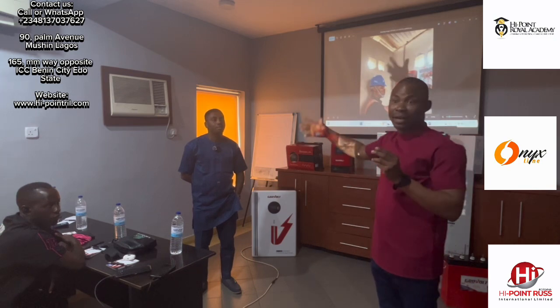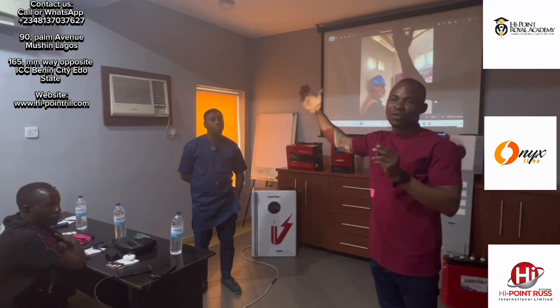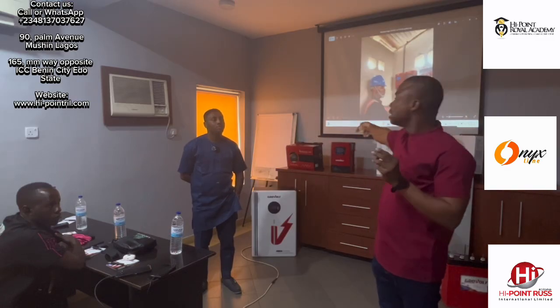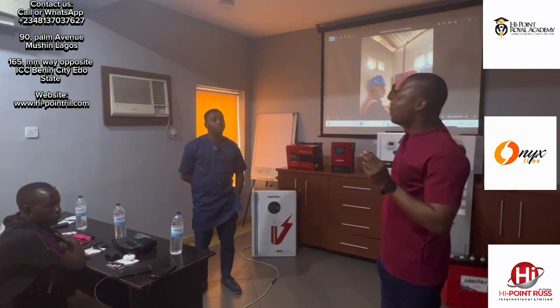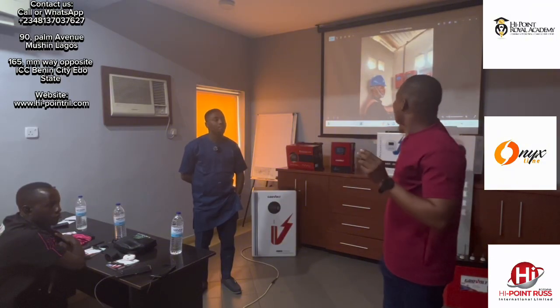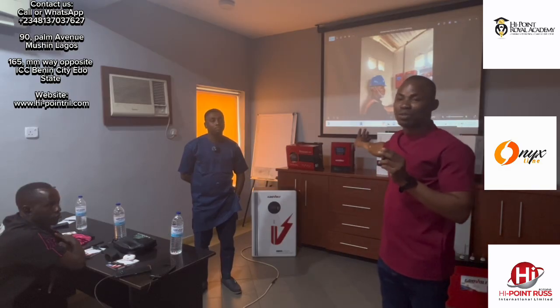We paralleled the three inverters. It's 48 volts for 3 phase: phase 1, phase 2, phase 3. Then the inverter feeds from the bus bar. The battery feeds the bus bar. The charge controller feeds the bus bar. Do you understand? So that's the battery bus bar.